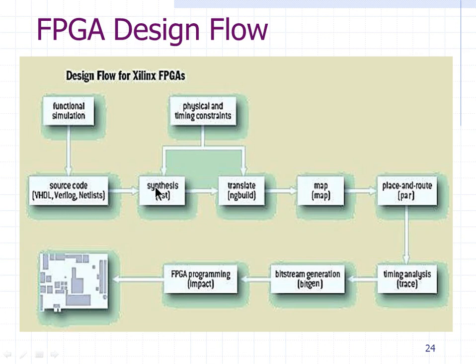So Verilog is then synthesized. This Verilog code will get synthesized or converted to netlist format. Then it follows certain other steps called mapping. This netlist is in generic, basic gates. Then it is translated or converted to Xilinx FPGA or any other FPGA or ASIC device components from that library. They are placed all across the chip, and the interconnections between all the components are done, which is part of placement and routing.